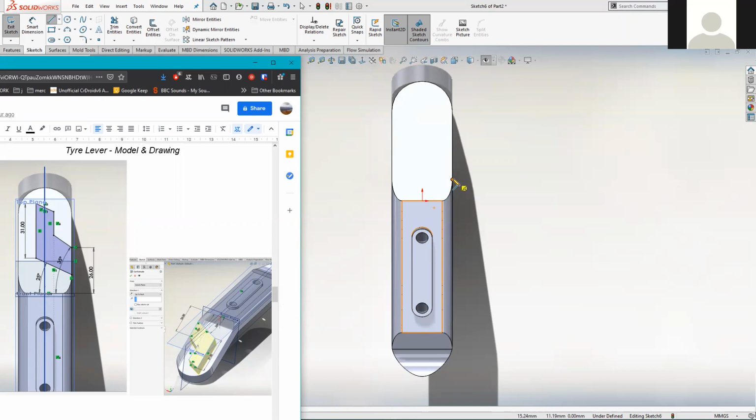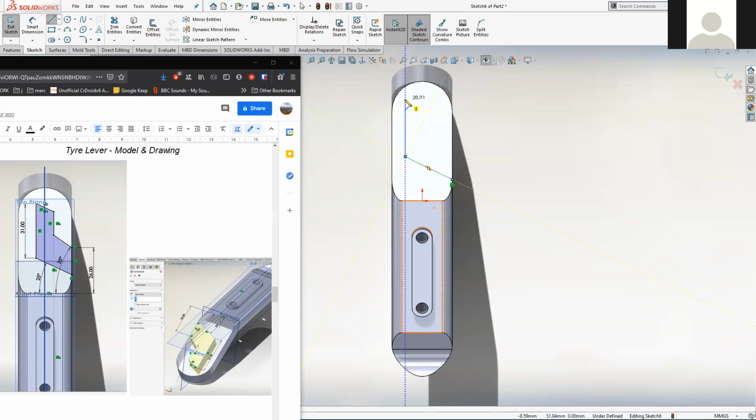But anyway, we can hover over the end of that fillet. You can see it tapers down to a point, and you can see that point being highlighted in orange there. When you're over the top of it and you've got the coincident icon, you can click, and I'm trying to match that screenshot that I'm looking at on the left hand side, so we'll click about there. I've gone too far there, but that doesn't matter.